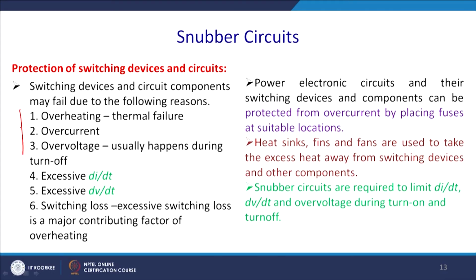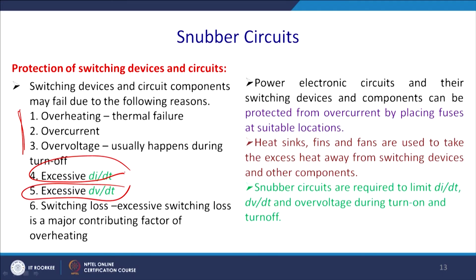So, these can be controlled by the supply side, but it may also cause excess di/dt and dv/dt. That may cause failure or reduce the lifetime of the switches, and also excessive switching loss while conducting. So, we need to reduce these two losses mainly by a snubber.